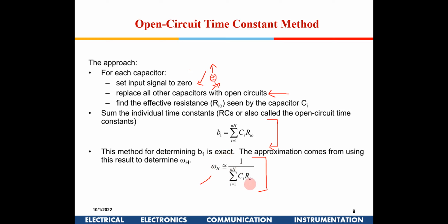Okay, so that we can do that, and to find out the mid band gain, you just neglect the effect of the capacitances, and then you find the poles, different poles, and with each pole you start taking the first pole, you take 20 dB, 40 dB, 60 dB, right? So this is how we go about it. So we'll do an example and things will be clear.